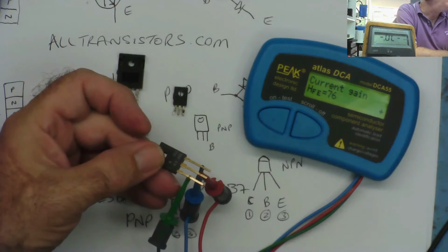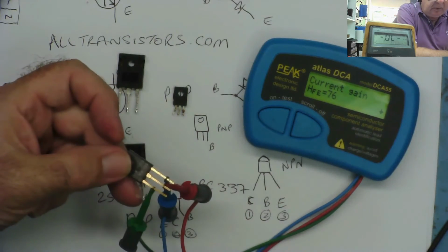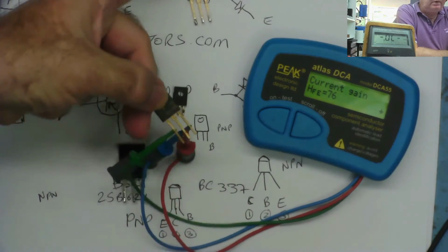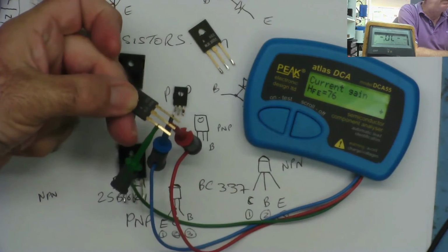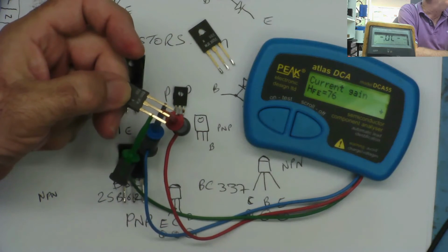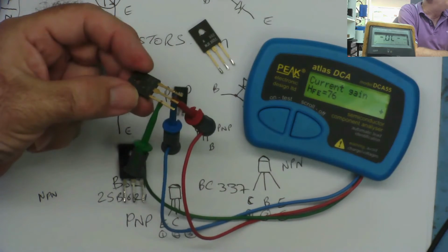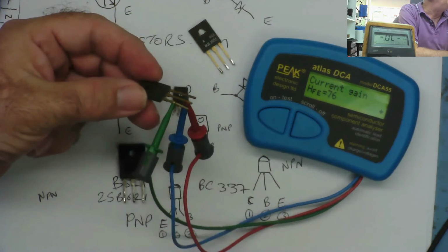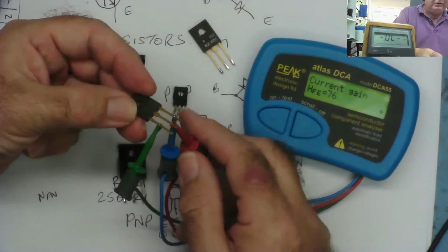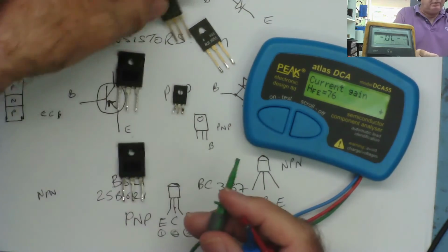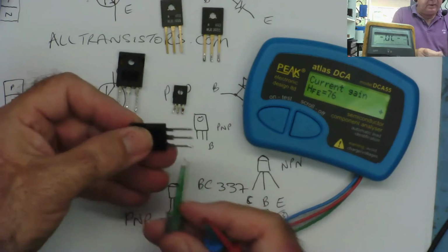That's a fair bit lower than the other one. I would say with these two, you would really need to go and look up the datasheet to see whether this one is within spec or not. This might be a bad transistor, or one with considerably less gain than it should have, and that could cause this to not work in circuit. So you need to at least go and look that one up. Yeah, we'll try in a minute.